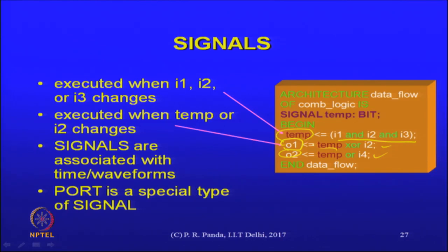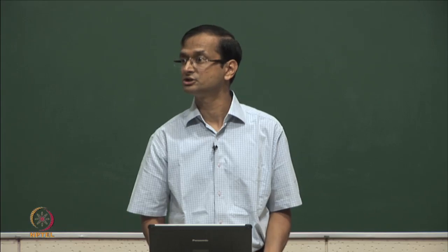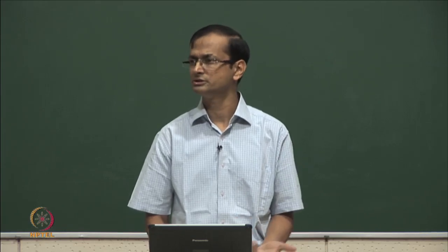Equivalent with respect to the functionality, with respect to the output, it should be equivalent. It is just that I1 no longer triggers O1 and O2 directly, which it did. Now it triggers only temp, but that is all right, because any changes in I1 are captured first in temp. If temp did not change as a result of I1 changing, did something go wrong? These expressions for O1 and O2 would not be triggered because temp did not change. That is the rule, which is okay, because that sub expression did not change, and therefore the whole expression also will not change.